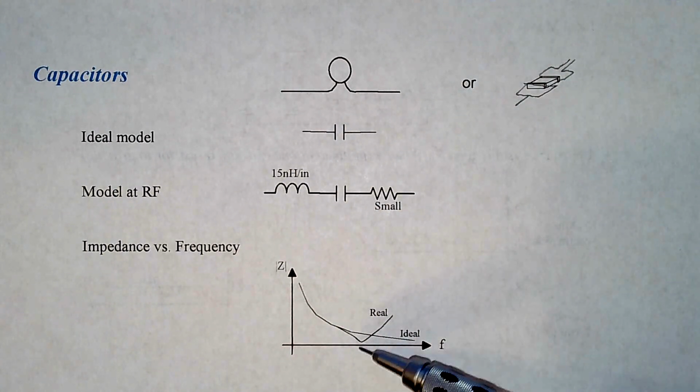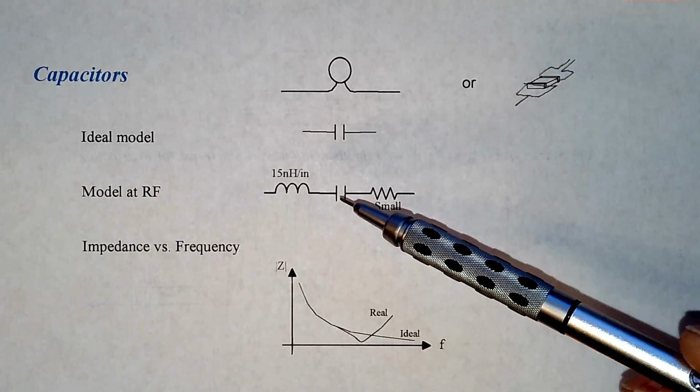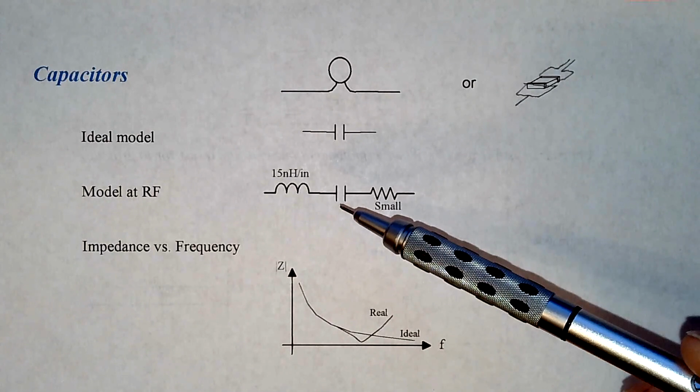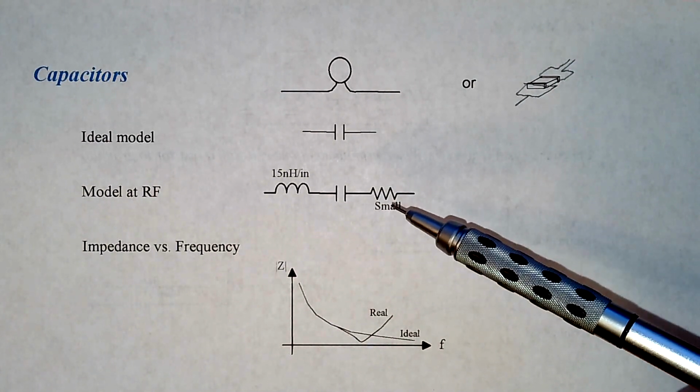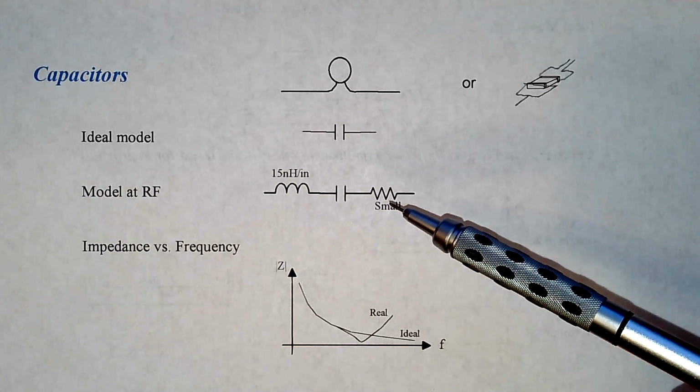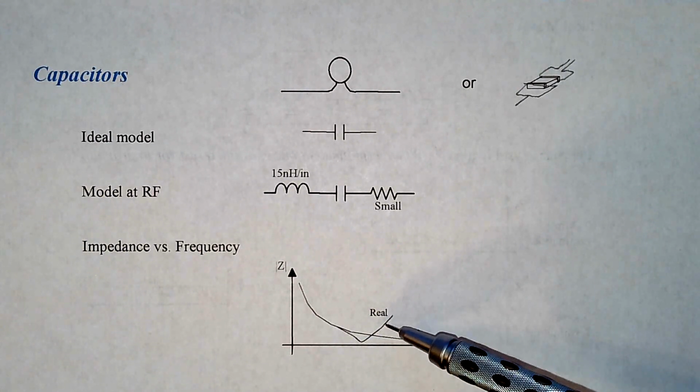That's shown here, but it's not shown as completely 0 ohms because there is some power loss in this capacitor which manifests itself as some resistance, and there may be some resistance in the traces or the capacitor itself or the dielectric materials. In any case, it dips to a minimum at some frequency and then it goes up.